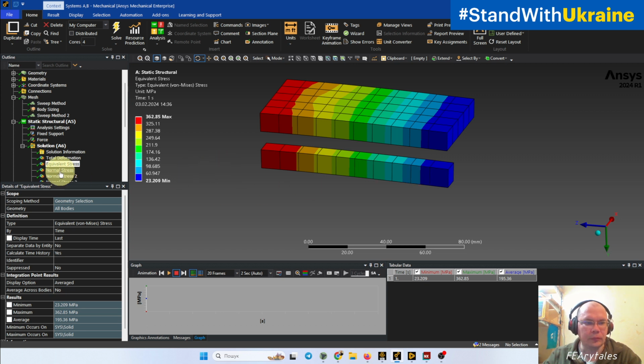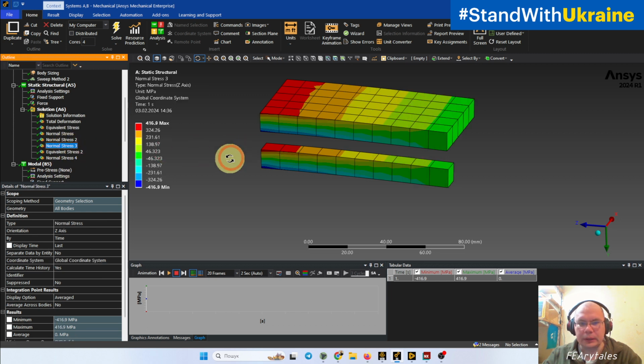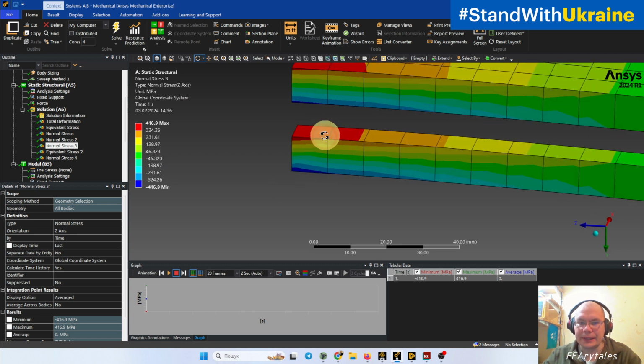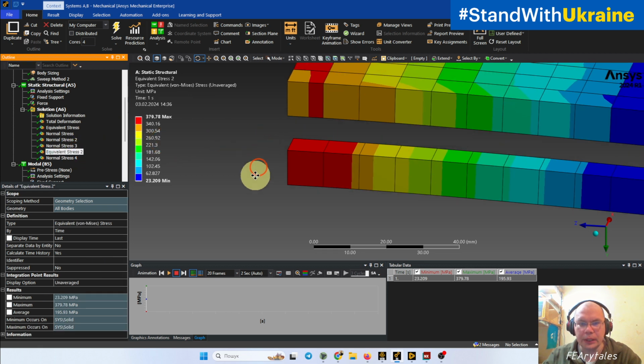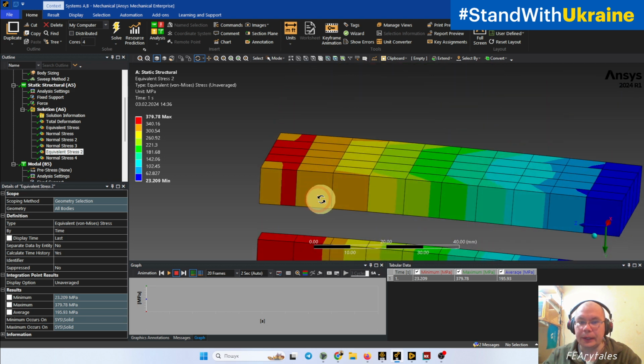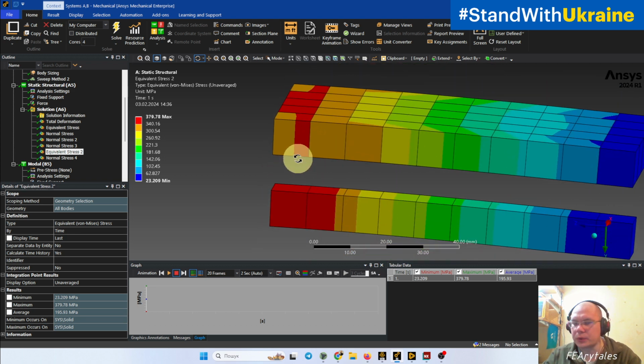okay. So we say that there is a linear distribution of tensile and compression stress along the height of our beam, and we see that we have linear stress distribution along the wall element for linear hexa. So it's almost okay, but the problem is the absence of zero stress in the von Mises picture.